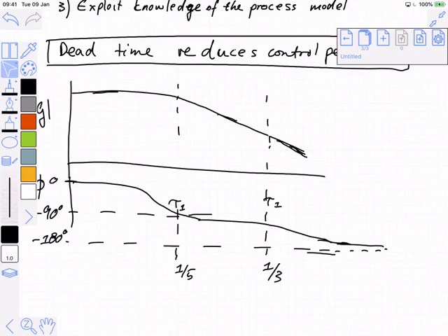And so in the frequency domain, this is an easy way to understand that first and second order systems with proportional only control have guaranteed stability. Because for a first order system, the maximum phase lag is minus 90 degrees, and for a second order system, the maximum phase lag is minus 180, and both of those systems therefore never reach this point. We can never find that crossover frequency, a realistic frequency where I'm looking at that gain.